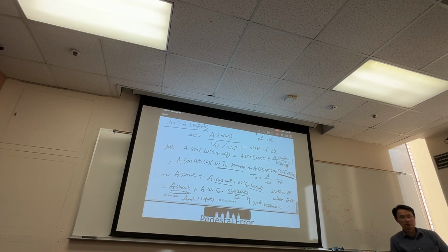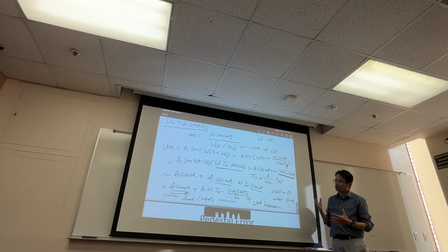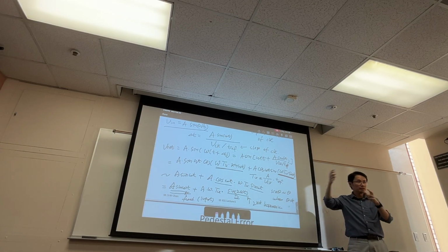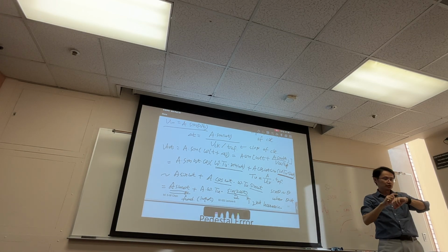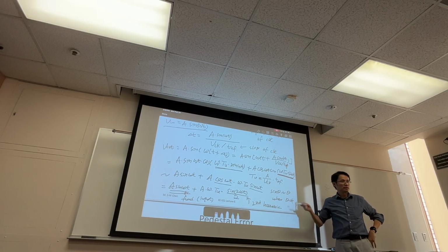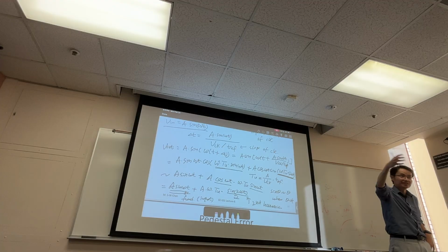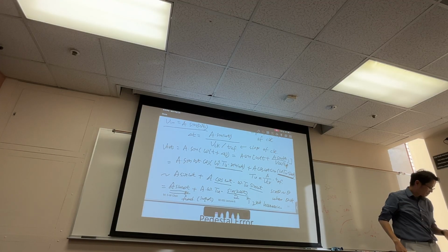Okay, so we're done. This analysis just teaches us what to expect. If you have this aperture uncertainty, because the actual crossing point, right, so your sampling instant shifts, what it comes down to is, congratulations, you get the second harmonic. This is why I said that when you look at the ADC output, you're going to see those spikes. So this is one of the many reasons.